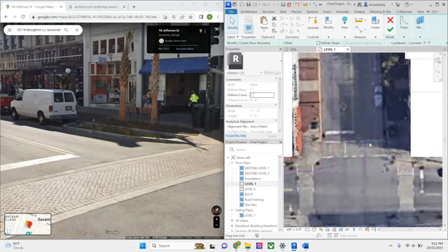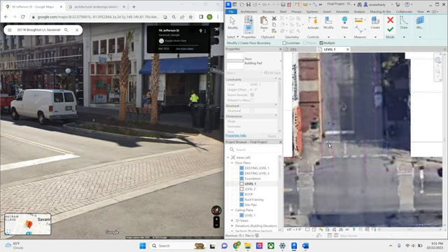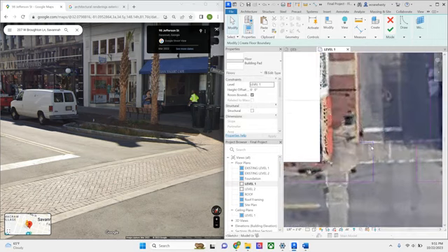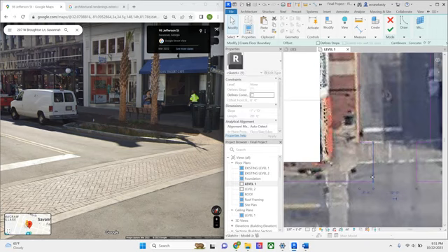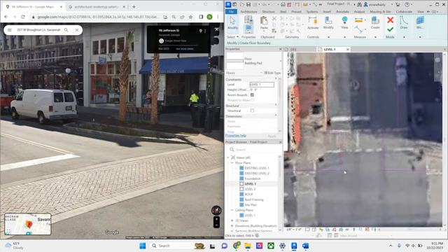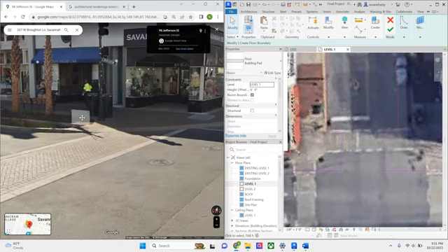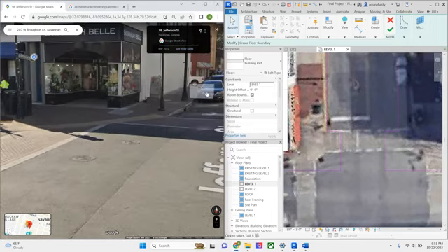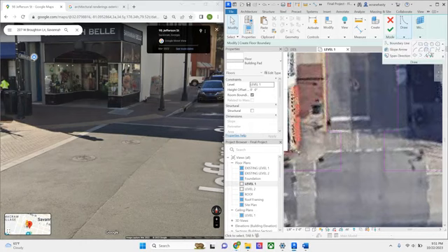So I will copy CO. I use my hotkeys quite often. So I'm trimming TR to get the corners, and I'm copying CO a lot. Mirror is MM. Move is MV. So I'm not coming up here and using these just because I'm so familiar with how this all works. But I do want to represent this radius that's coming all the way across. So I'll probably come up here, do the fillet arc.